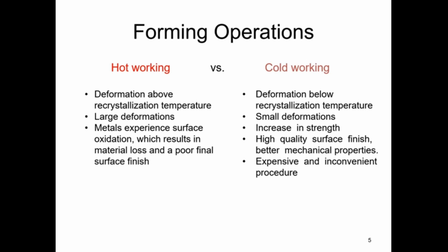While for cold working operation, it will produce metal alloy with increased strength, and the quality of the surface finish is much better as compared to the hot working operation. And of course, mechanical properties are much better than the hot working operation. However, cold working is much more expensive, and the procedure is also quite inconvenient.